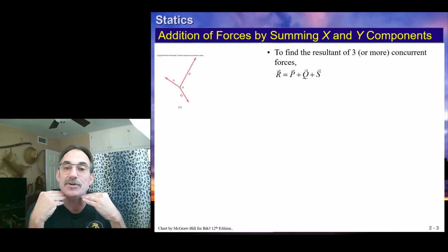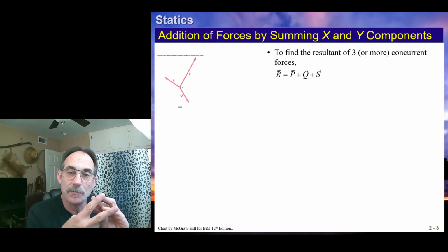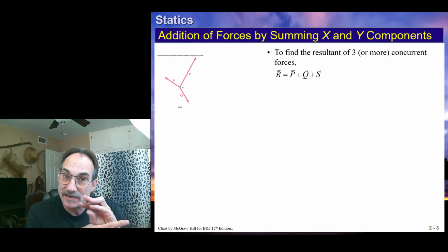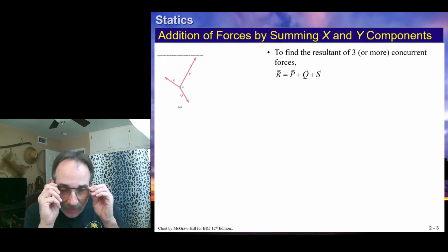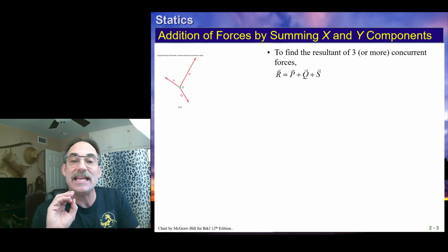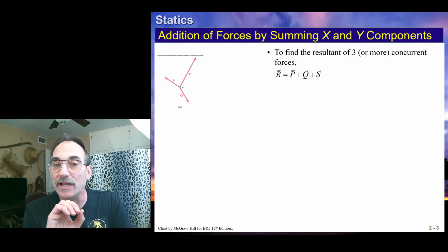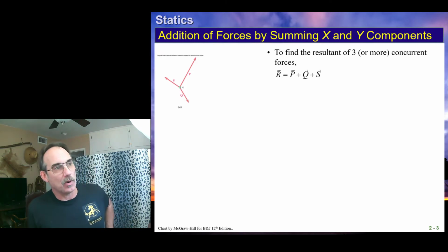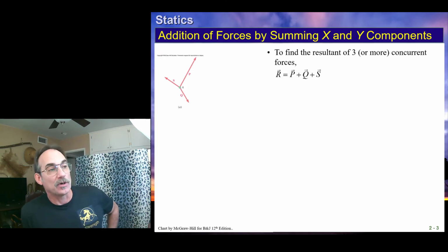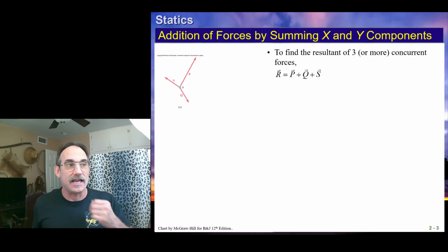If we had used the methods from last lecture, we would have taken two of these, put them together with our force triangle, and then taken the resultant with the next component and done it again. But with rectangular components, it's even easier because we can just define each force vector with its components and the unit vectors, and then put together those component forces. So R, that resultant, is actually an equivalent force, because we're taking all these forces and coming up with the equivalent force that they generate.